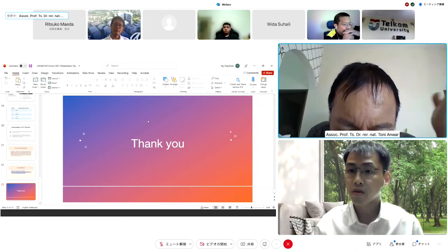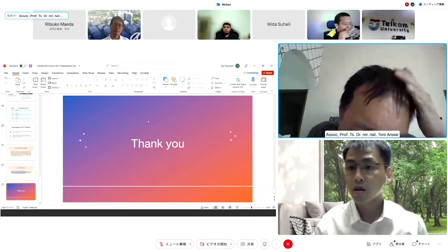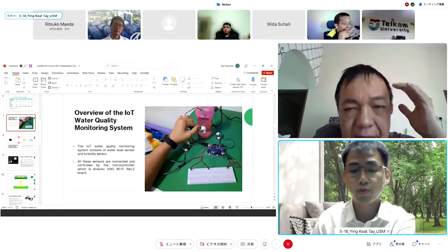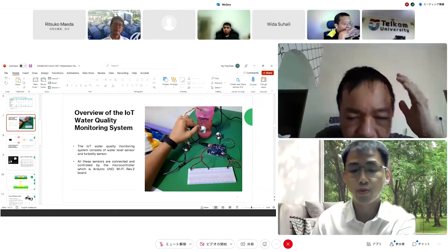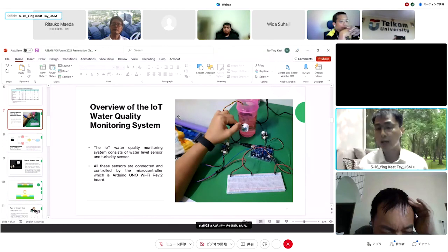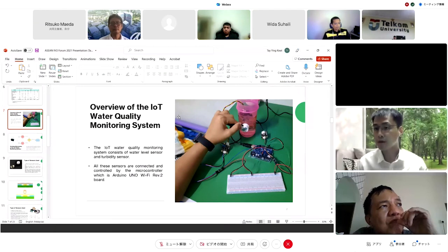Because you just connect existing products in the market. All right. What is special about this project is that there are a lot of water reuse systems, but many of them have failed because of a lack of maintenance and monitoring. So we try to solve this issue to make these water reuse projects succeed. We deploy the IoT water quality monitoring system to these water reuse systems so that they can be monitored remotely.